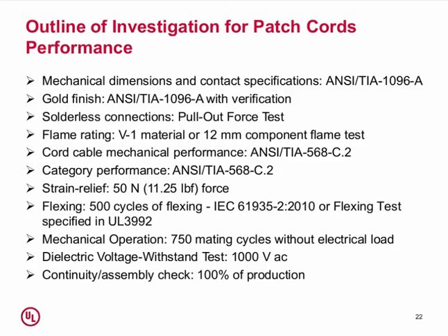Flexing test. In earlier UL standards, like UL 1863, there was not a flexing test. And yet we find out, especially as we go into lighter gauge cabling, that flexing is one of the areas where there's a lot of failures with patch cords. So the flexing test was adopted from the IEC document, or there's a separate flexing test that was adopted from UL 588 that's actually in 3992.